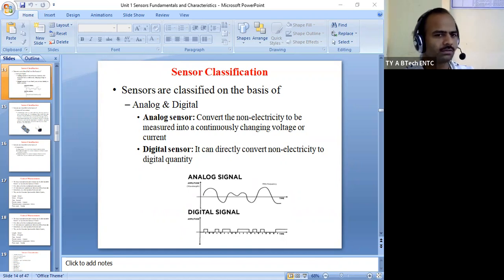If you are saying that particular customer, it is not possible to measure the current without cutting the wire, so we have to make two terminals where the wire is cut, and then we insert our multimeter or current sensor, and then we extract the current and display it on our system. Okay, but if you do this, then it will be limited to only that position. Suppose a 200-meter wire is there, you have cut it in between at 50 meters, making two terminals, and you are inserting your multimeter for measurement of current. It will be shown, or some current sensor, and again you extract the readings.